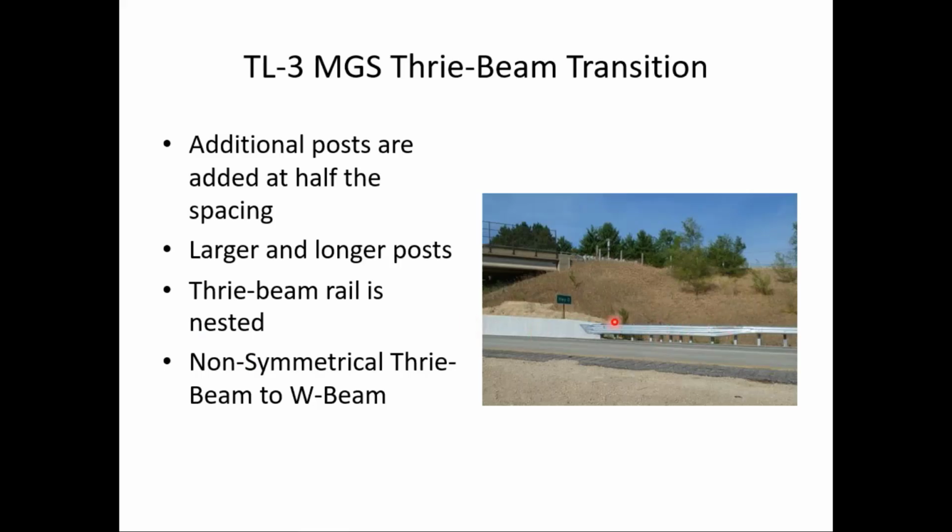And this section here is what's called the tri-beam. This is a newer design. Notice it's deeper than the standard W-beam. So one of the advantages is it can accommodate a wider variety of vehicles, from a small vehicle, maybe with a low bumper height, to a larger pickup truck that might have a higher bumper height.